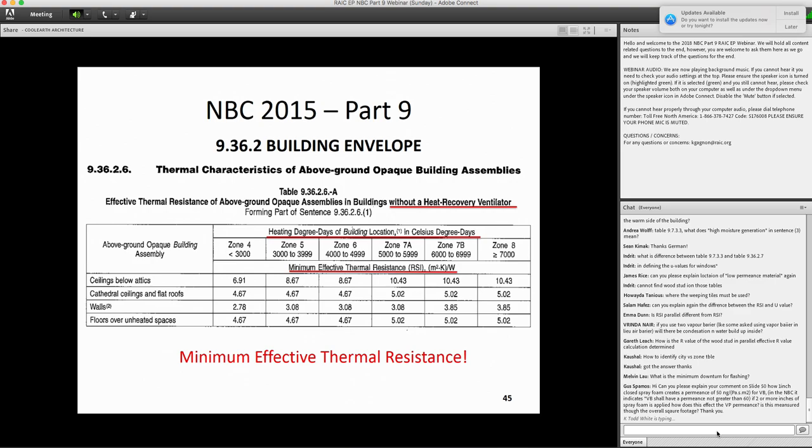Is exterior spray insulation problematic because it is not on the warm side of the building? Somehow it is. I guess you're talking about closed cell spray foam. Closed cell spray foam doesn't have permeability, so any moisture that you might get in between that exterior closed cell spray foam and the interior vapor barrier will not be able to dry out.